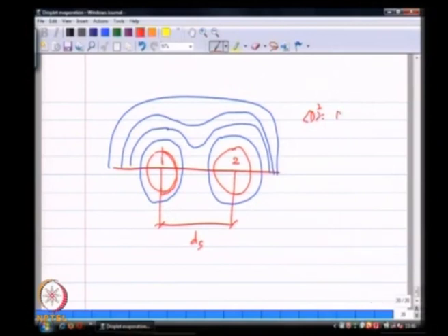And so, this causes a different rate of evaporation on the two drops, which means that I still may be able to use something like a d squared law, but this is now a function of the droplet spacing, like a mean droplet spacing, and this is again an area of active research to extract information that relates to multiple droplet effects.